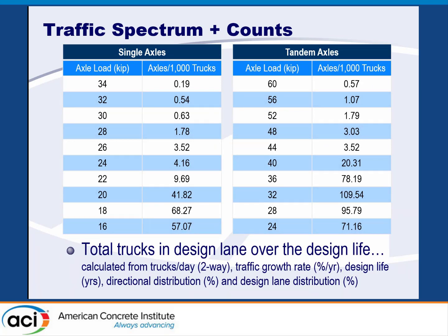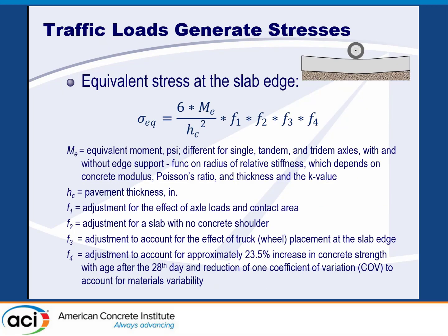And so Pavement Designer actually incorporates a lot of the traffic spectrums. If you remember the table that I showed from the 325 guide, it has those spectrums built into it where we can see the actual axle loads that are in a spectrum and then the number of those axle loads that our pavement's exposed to. And you'll see how that looks in just a second.